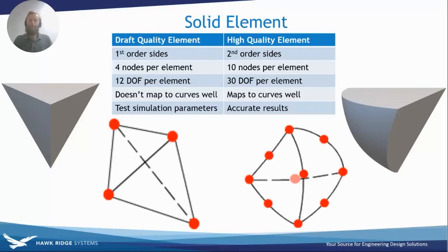So when you say the weld tool, sorry Dorian, this is your question. The weld tool does create simulation usable geometry. You just need to be a little more specific on what you mean by weld tool. If you're using weldments, then those weldment structures are automatically created as beam elements.